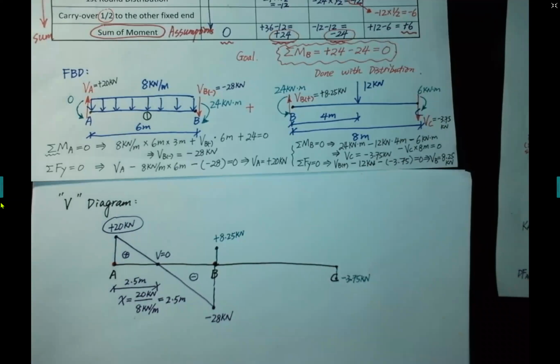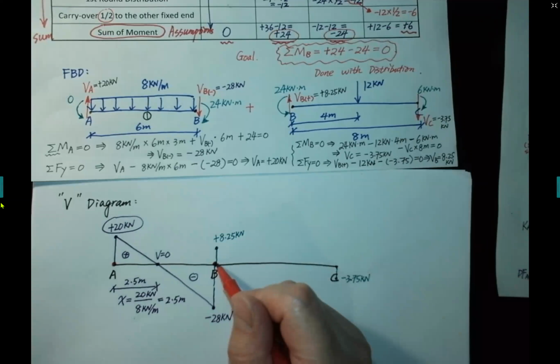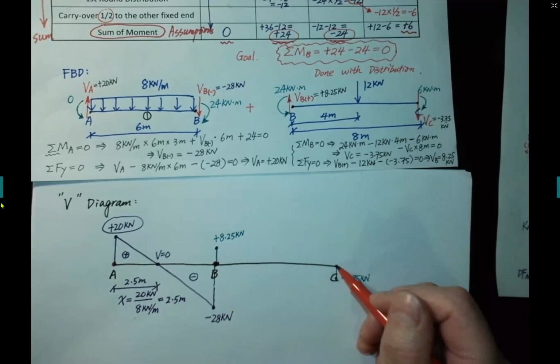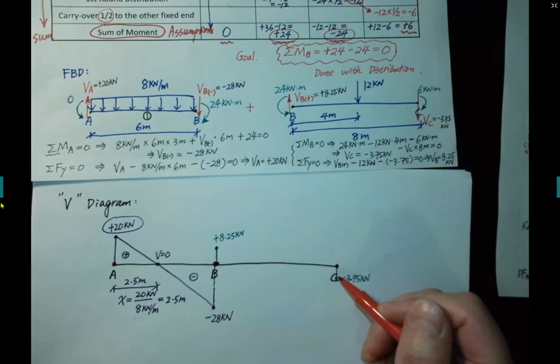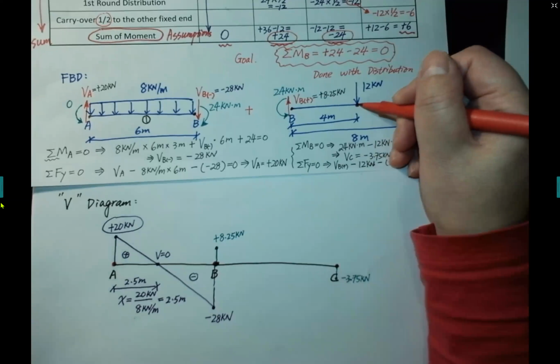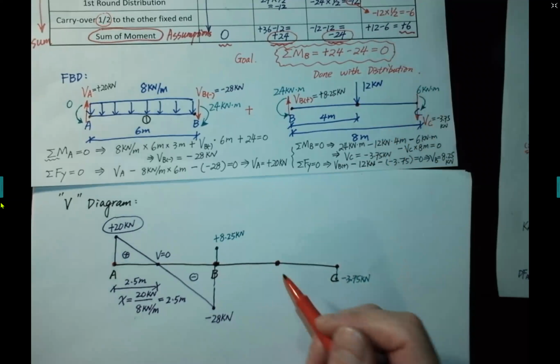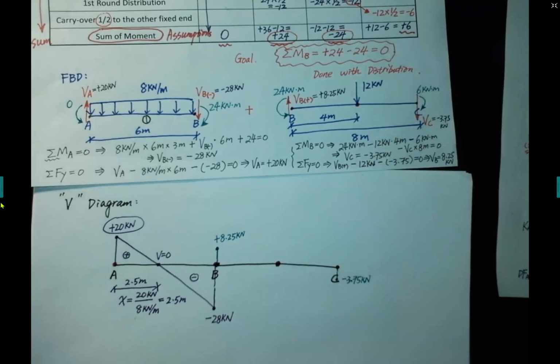In order to identify the key points of shear force on member BC, first we identify B is a support, C is the beam end, and there is also a point that has an external load change. So it's right here, the point load location. For shear key points, we also need to identify the point under the 12 kilonewton load.